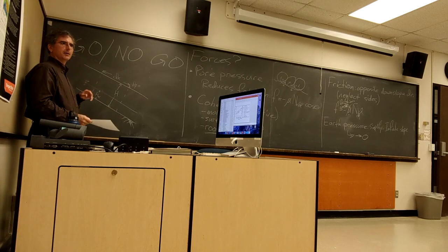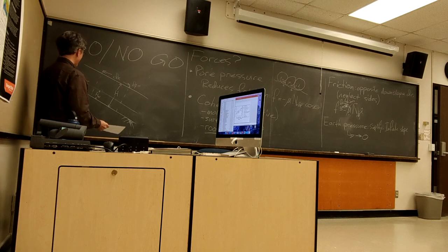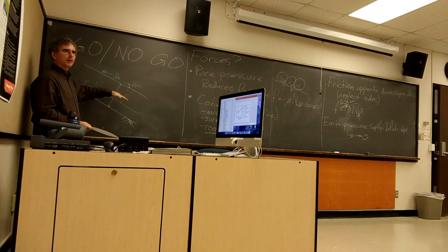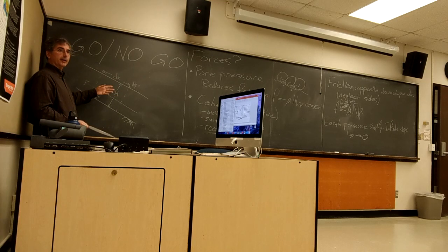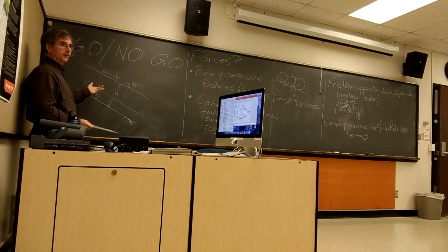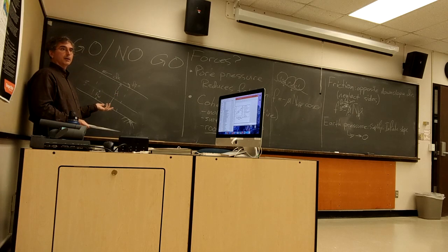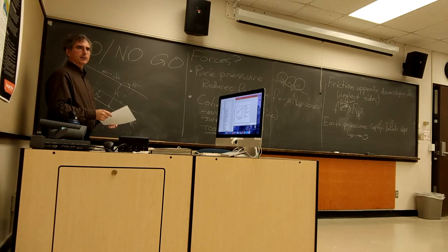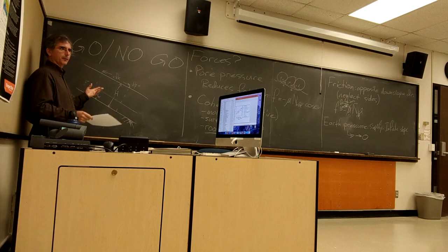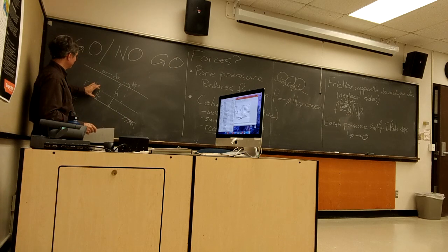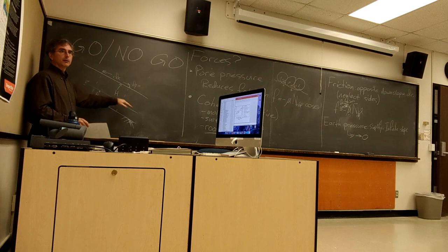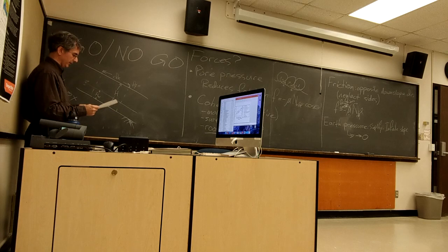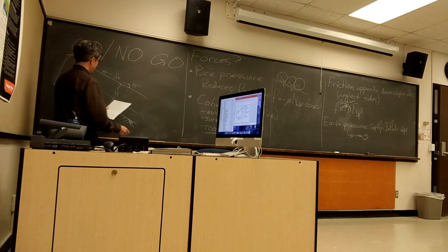Because it does actually matter in this case whether the water table is parallel to the slope or flat. And in this case, we're going to assume that, well, we are on a slope, the water is moving. It's not, say, dammed up behind some road fill or something like that. Again, we're dealing with an infinite slope situation, and so we have water flow parallel to the slope, and so our water table has that sort of thickness look to it.